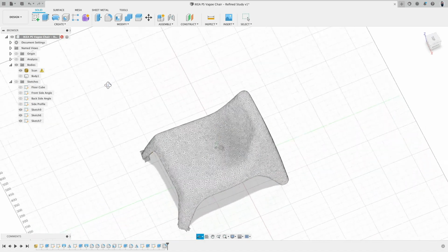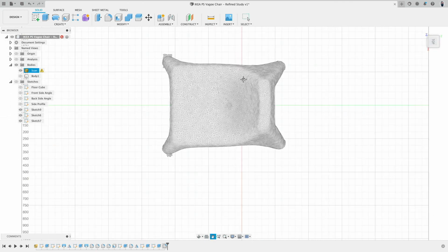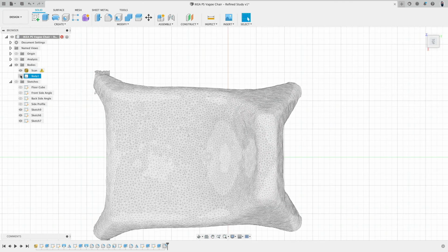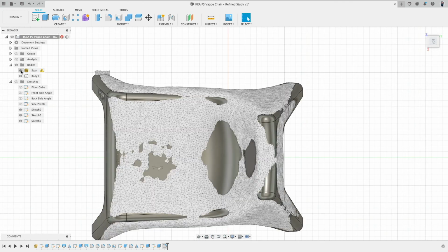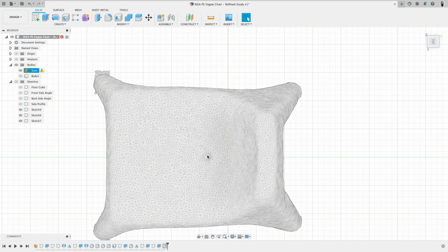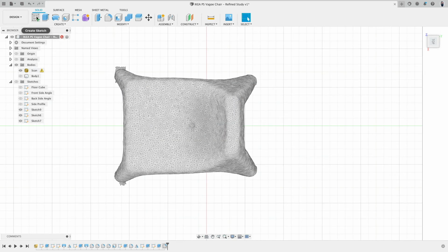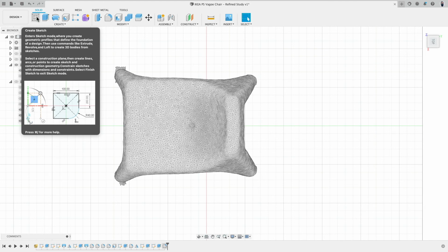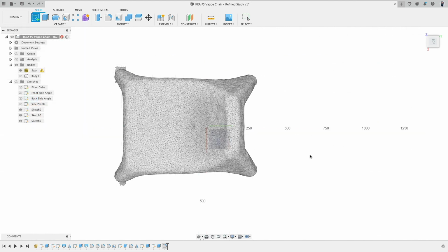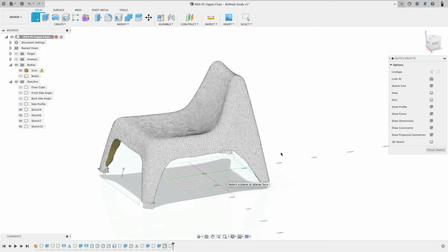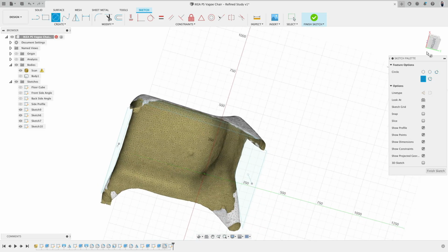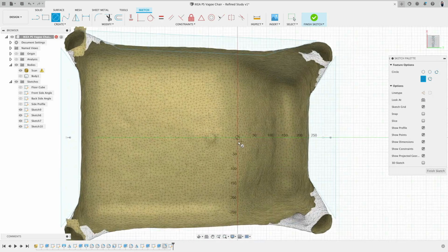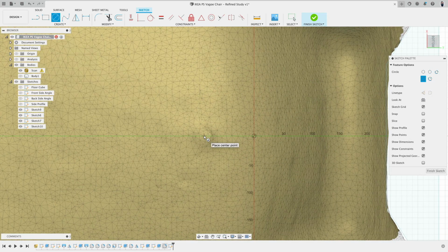The last piece that's maybe left, tiny detail. So when this is outside and it rains and water flows on it, we want water here to pour out. So how do we get there a hole in? Very easy. On the ground, ideally I will look from the bottom, that's easier to see. Create myself a small circle, maybe like this.